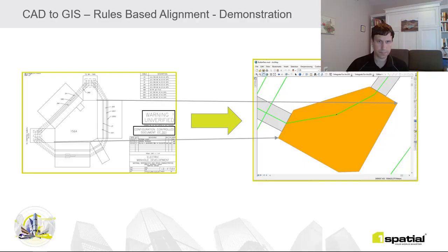In this case, we were working with one floor, but now we can apply this to all of our floors for all of our buildings, and we can do it in an automated way. And this can be done repetitively. So as the CAD drawings change and update, we can then update our GIS and then flag the appropriate workflows of what needs to occur after those changes have been committed.